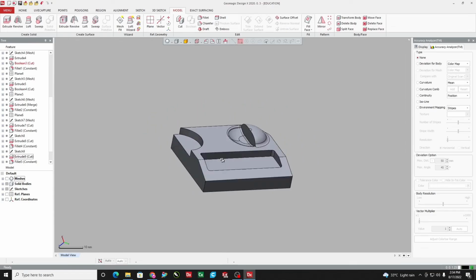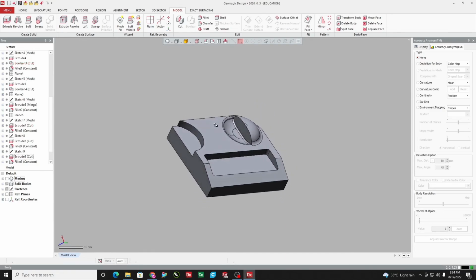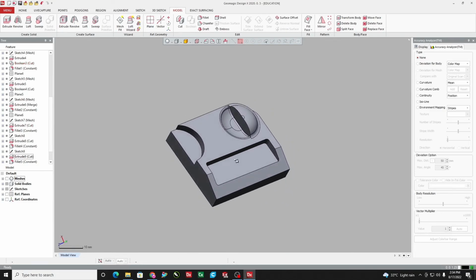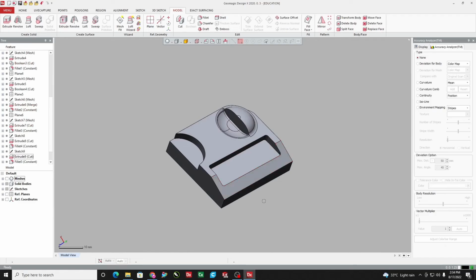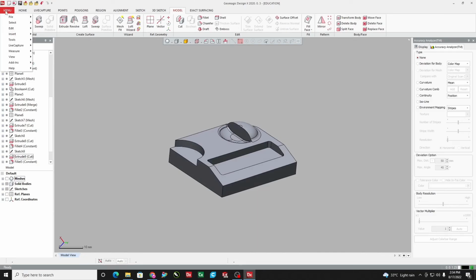There are multiple other things that could be taught or that could have been missed in this lecture. Though the learning of the 3D printing process, I have just shown you the major steps in data capture, the data cleaning during the capture itself, the alignment, the selection of certain parts when we start creating the plane, and also how we cut and extrude. Just like we work in other solid model development, we work on data cleaning or data editing using the software Geomagic Design X. We try to keep it matching using the accuracy analyzer and see how close it is to the obtained mesh object. This is how reverse engineering works.